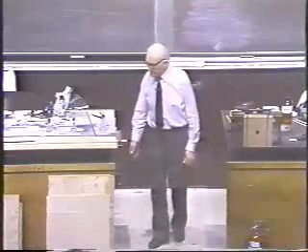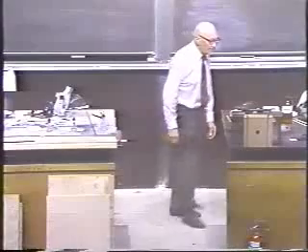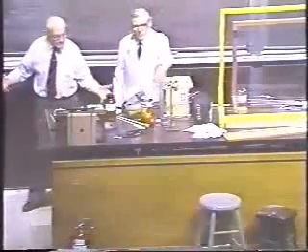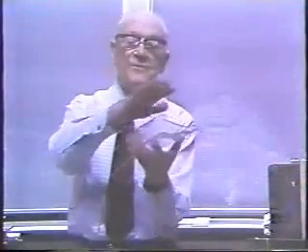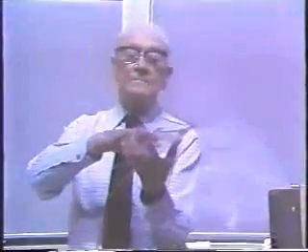However, an allied application is explosive welding. Some metals cannot be joined by any conventional welding technique, for example, steel and titanium. But if you have a base plate of the one and a sheet of the other, and put the second one over the top, cover it with sheet explosive and then detonate it, as it slaps down, the two are firmly welded together.